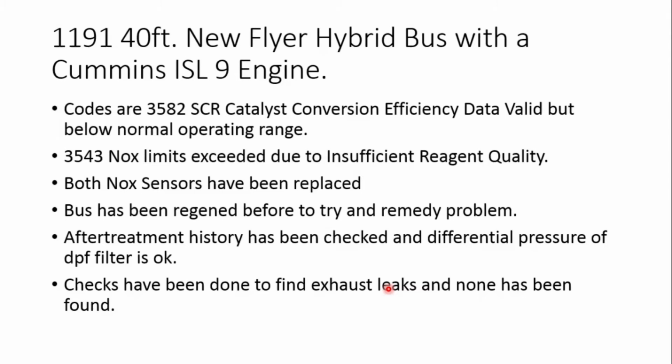History, what's been done already. Both NOx sensors have been replaced. We've regened it before to try and remedy the issue. The after treatment history from Insight has been checked, and the differential pressure of the DPF filter is fine. We've also done checks to look for exhaust leaks, and none has been found.